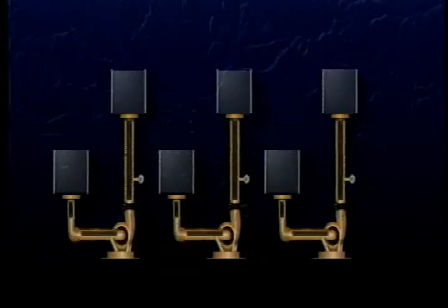An important factor which often affects static head is the weight, or the specific gravity, of the fluid being pumped. As you would expect, the heavier the fluid, the greater the head the pump must develop. The weight of a fluid is usually compared to cold water, which has a specific gravity of 1.0. A pump working against a head of 105 feet of water will not be able to pump a heavier fluid as far unless it works harder.